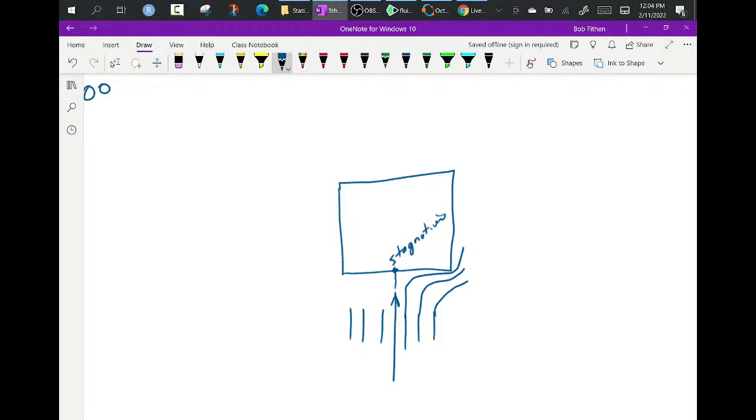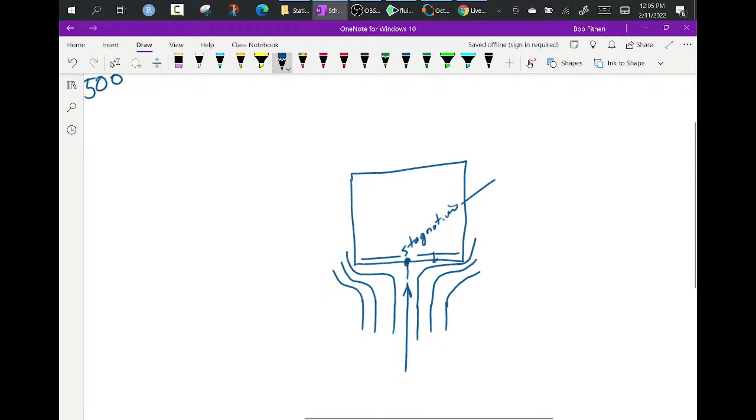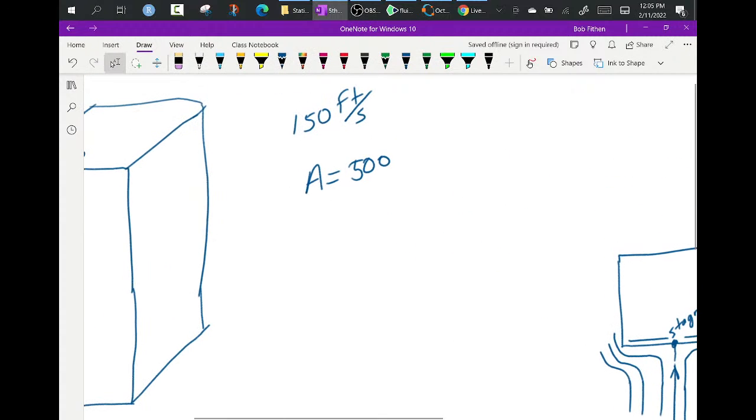Now, in the effort of turning these particles, the pressure is higher here, but it will not be as high as the stagnation pressure. So what I did in this particular problem is I said, well, what if this stagnation pressure is distributed across the whole surface? That would be a very conservative estimate, because the stagnation pressure is the highest pressure you can get. And so let's look at this: P plus gamma z plus rho v squared over 2 is equal to a constant.